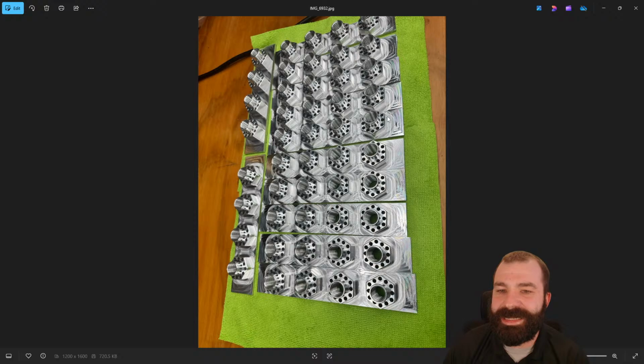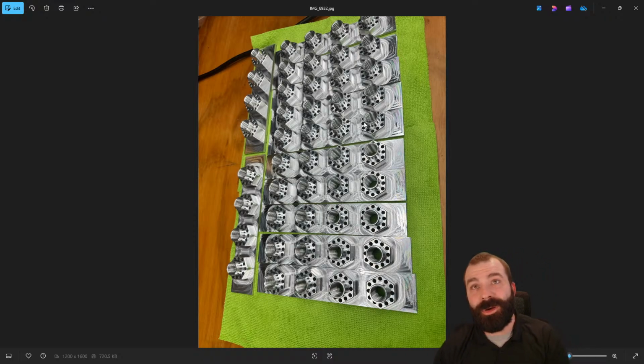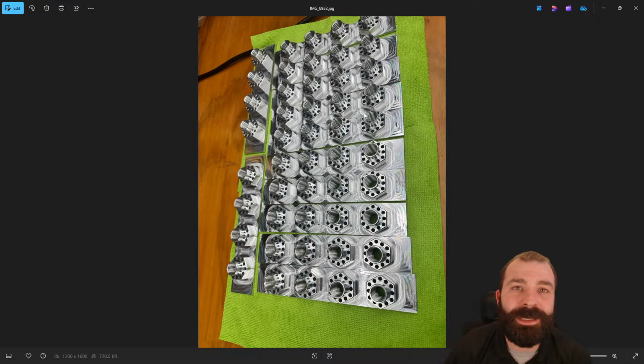Jeff, it's a little hard to say even what the back side of this part looks like, because again, I'm not saying the way you did it is wrong, but had we done the hex size first, right, we could actually use that hex side and then do the inner groove and then all the through holes back the opposite way. So again, every part is different. The way you think about doing it and the way you achieve it, night and day different results, right? Now, keep in mind, if you did do this front side first, you could always get a pallet to hold on to the outside to keep it on center as well.